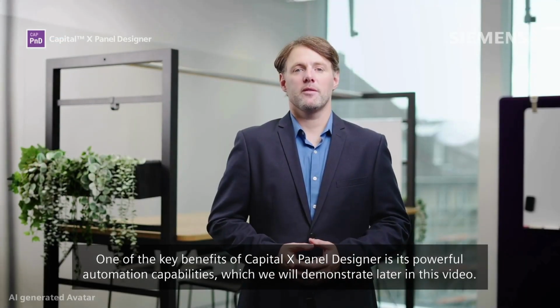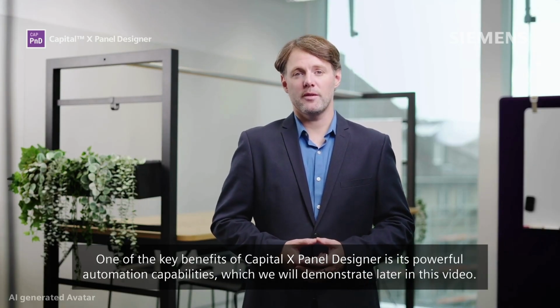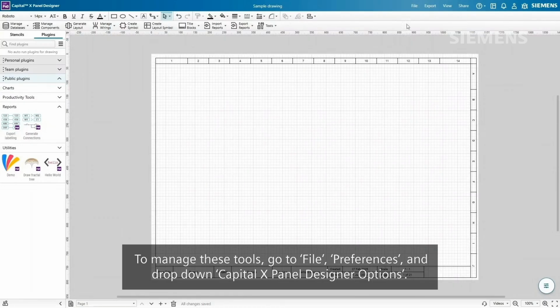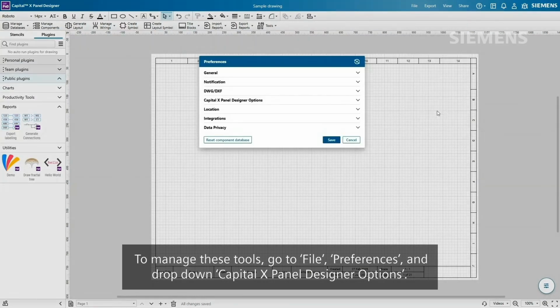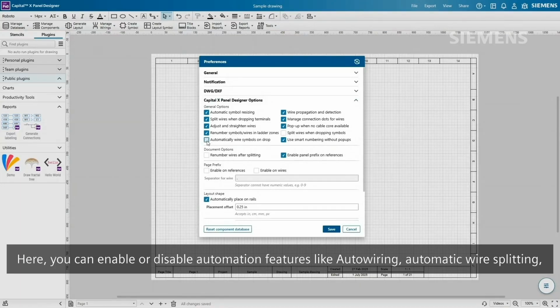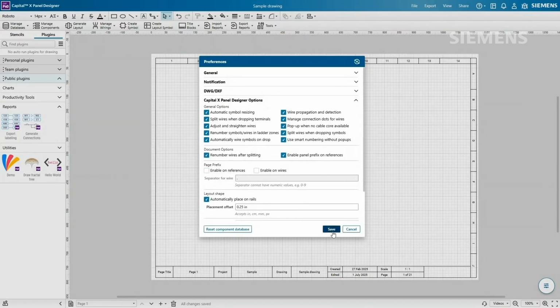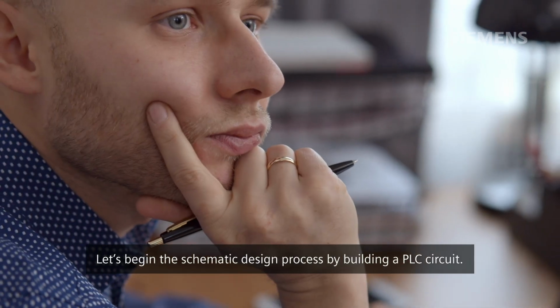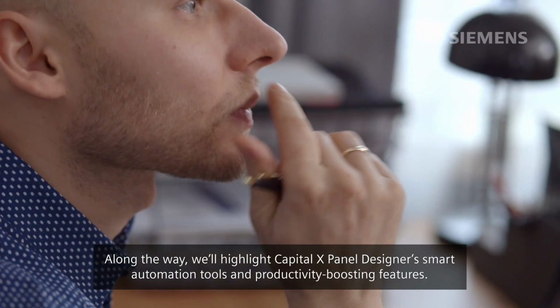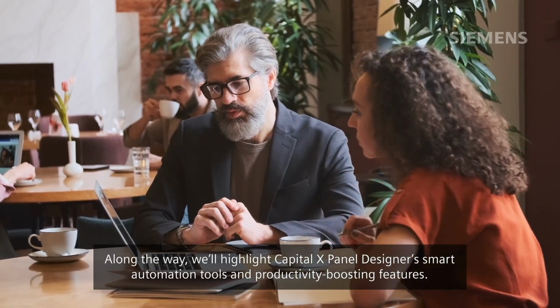One of the key benefits of Capital X Panel Designer is its powerful automation capabilities, which we will demonstrate later in this video. To manage these tools, go to File, Preferences, and drop down Capital X Panel Designer options. Here, you can enable or disable automation features like Autowiring, automatic wire splitting, and smart renumbering based on your workflow preferences. Let's begin the schematic design process by building a PLC circuit. Along the way, we'll highlight Capital X Panel Designer's smart automation tools and productivity-boosting features.